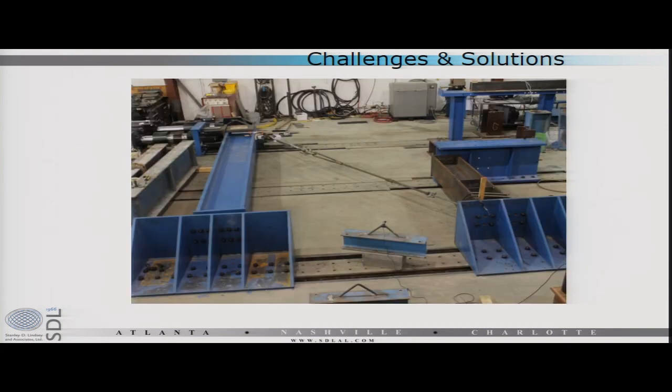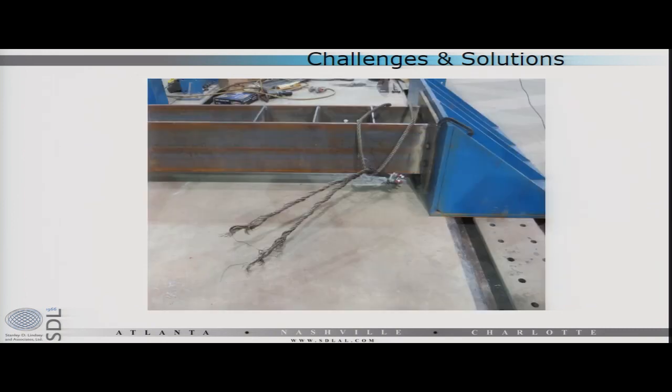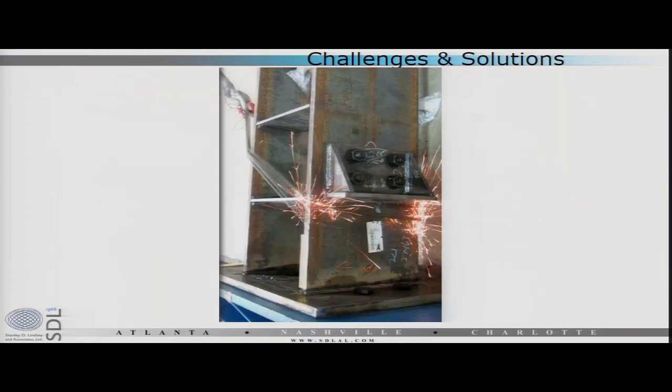And the cable itself was oversized. We were trying to force the failure to occur down at the connection to see when this would break or slip, etc. And so we varied the angle of the cable. We pulled up on it at 45 degrees, 50, 60, things like that. And more often than not, we ended up with this, where it stayed right where it started and we snapped the cable in half. However, at higher angles, we ended up with this. We had a stop angle on there to prevent it from rising, in infinitum, but it did slip. And this was a well-timed photograph that shows it in the middle of slip. So it does happen.